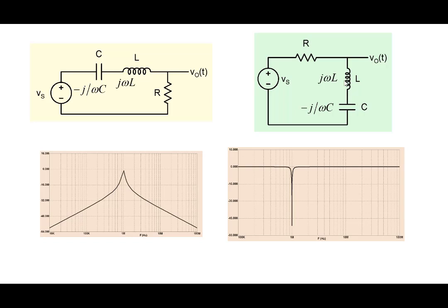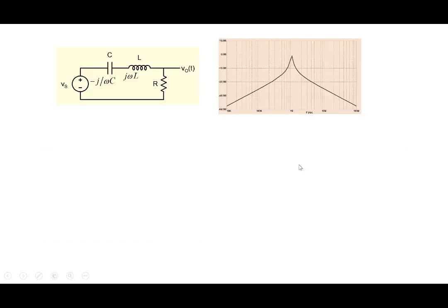And despite the best efforts, sometimes a little bit of AC voltage may remain in the power supply, and that AC signal can get into your circuit, and you're interested of course in removing it. So what you could do is pass your signal through a band stop filter at 50 Hertz, and thereby any 50 Hertz signal that gets through is rejected, and everything else is passed.